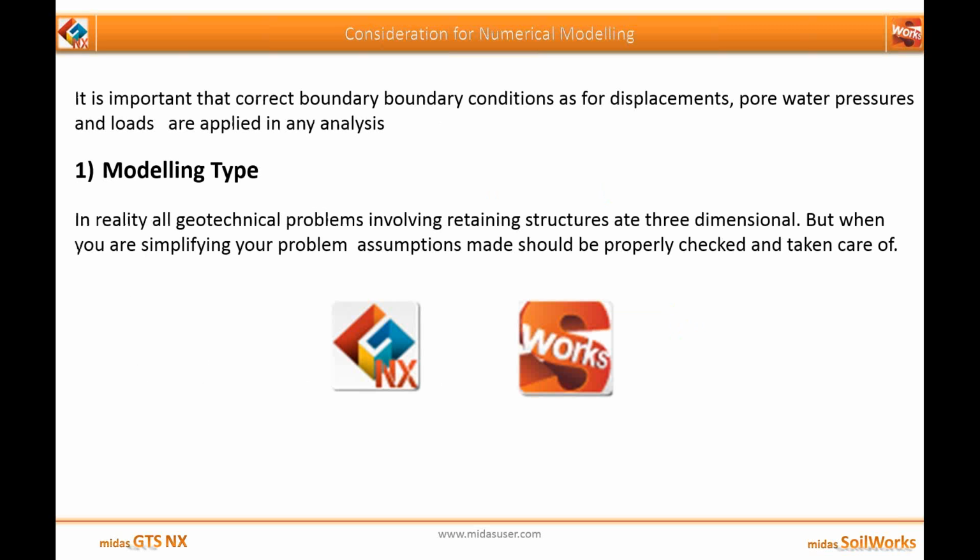Now, what are the various considerations when you go for numerical modeling? First, it is important that the correct boundary conditions for the displacement, pore water pressure and loads are applied in any analysis. The first consideration is modeling type. In reality, all geotechnical problems which involve retaining structures are three-dimensional.